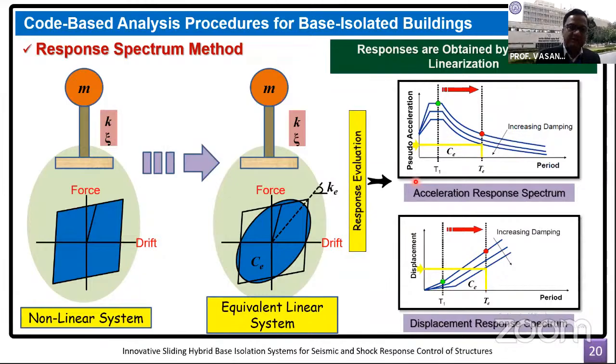There is a practice of using the linear response spectrum, in which for the nonlinear isolation system, we convert the force deformation loop into an equivalent stiffness and damping force deformation loop, and then we can still use the linear response spectrum. So for that equivalent linear system, for all practical purposes, we are able to obtain results satisfactory enough for conducting the design.